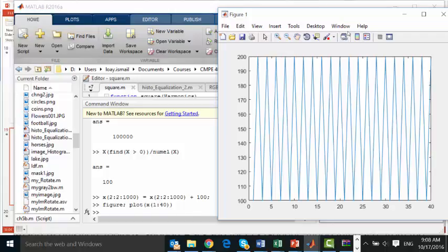This signal actually, what is the frequency of changing this signal? This means that for the whole range from 1 to 1000, this form of signal will be repeated how many times? 500. So this means that at the frequency 500 as well, I expect to have another non-zero value. And all of the other values of the frequencies, I expect to have what? Zeros. Okay? Let's prove it.